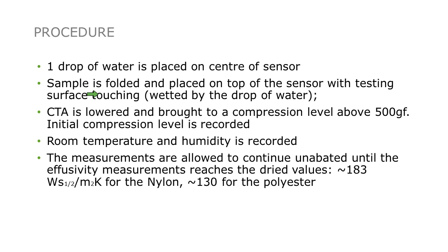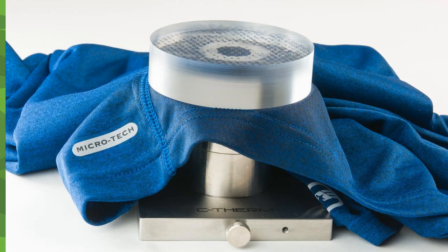But again, whatever side is going to come in contact with the human skin, that's the side that you would want to interface with the sensor. In this particular data set that we're going to look at, the compression test accessory was used with a 500-gram force. We do also see opportunity maybe to simplify it a little bit in testing wetted materials and using more of a puck or a weight as a material to just put a little bit of compressive force and making sure there's a good intimate contact between the sample and the sensor.